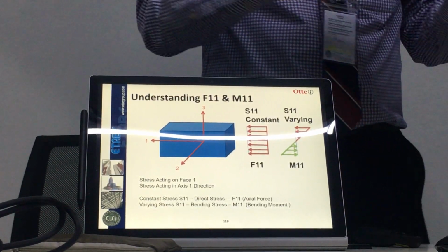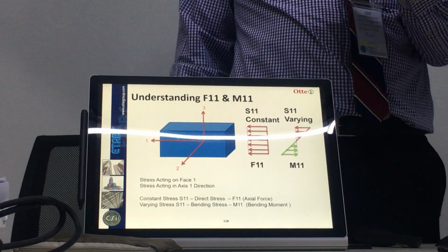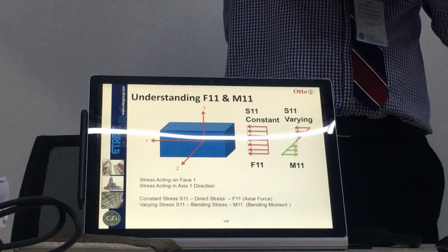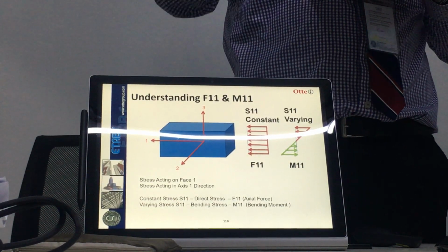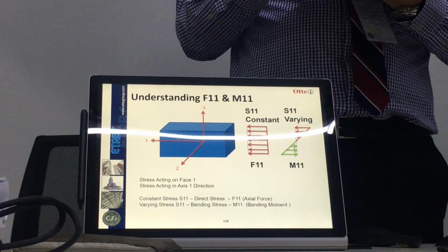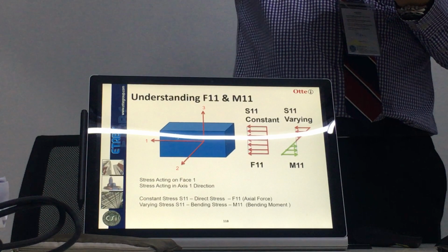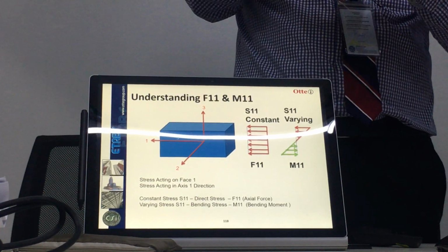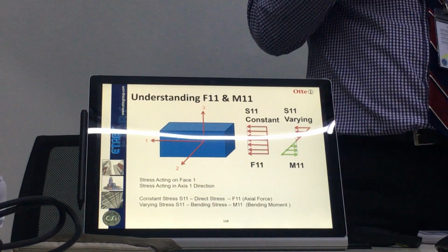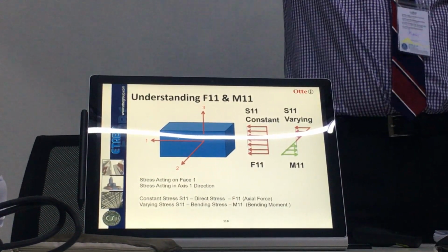So if I put my rebar this way, my bending is which way? Must be this way, right? If I do it this way, the rebar doesn't do anything. It cracks the slab. It's this way. So M11 has the rebar. Let's imagine this is 1. M11 has rebar in this direction and it's bending along the same direction. So that's how we remember it. M11 requires rebar in the 1 direction, so it's bending along the 1 direction.